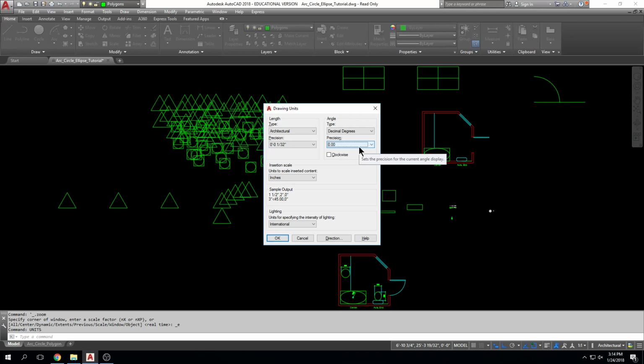So when architects and engineers or civil engineers interact, I call a civil engineer and I say, hey, I'm working on this project. Can you send me the CAD file for the site plan? They'll say, yeah, sure. They send over the site plan. Then before I can use it, I have to scale it up by a factor of 12 in order to make it the correct size to put architectural items on, okay? And that interaction goes on all the time.